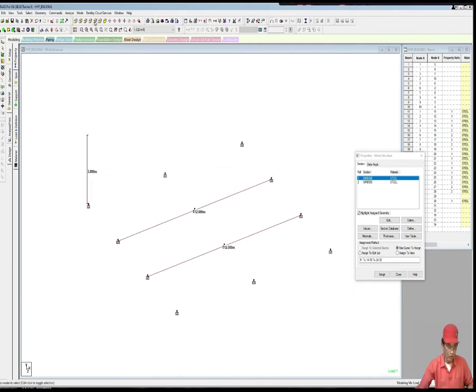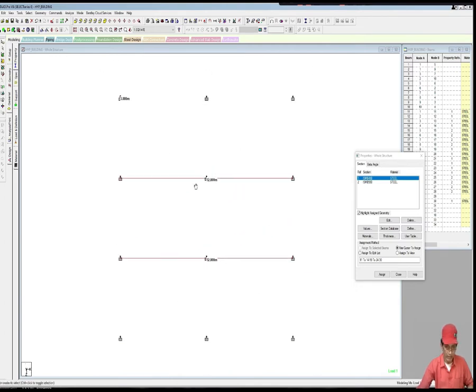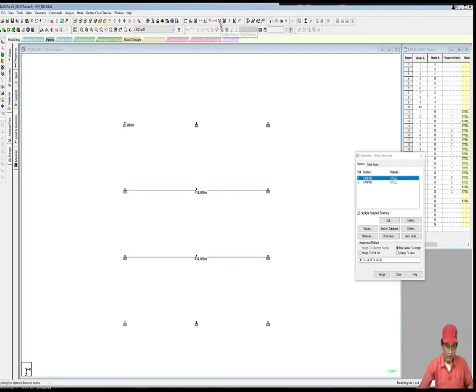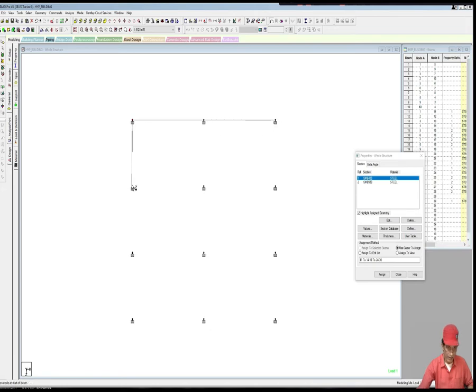So go to top view. So we have this view here. Now go to display, node to node distance. Remove node to node distance. We now select the beam cursor on select, and create all the beams at the periphery first.